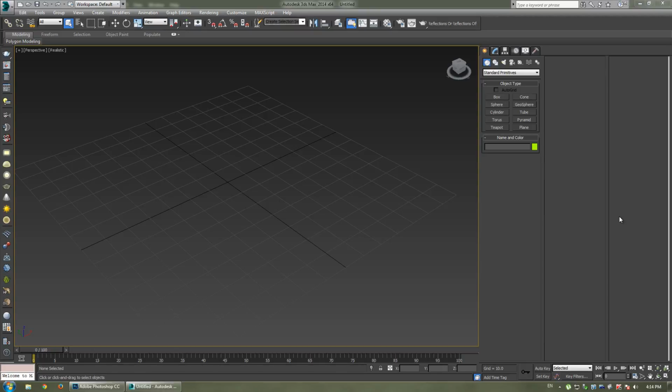But moving on from lesson 1, where I showed you the very basic hotkeys and tools that are going to be utilised throughout the course, I can now begin to move on to the fundamentals of the geometry creation and cleaning process. I can't stress enough the importance of cleaning your meshes as you go. So in order to do that, you need to make sure your meshes are as low res as possible. The easiest way we're going to do that is by utilizing the show end result mode while modeling, so you can visualize the final result and know that you're not adding too many edges to your mesh.